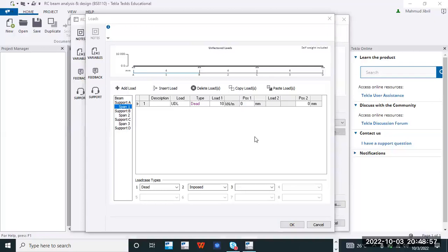Normally we encounter those kinds of issues, especially when dealing with residential buildings, where loads are transferred from slab to beams. You will normally see those loads as part UDL on the beam. That is, they do not occupy the whole length of the beam. They occupy some certain position of the beam. So on this one, the load will start from the endpoint here and go to the other endpoint, which is 4 meters, and then click on enter.